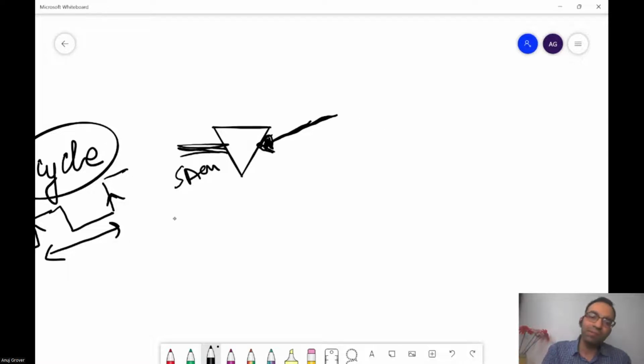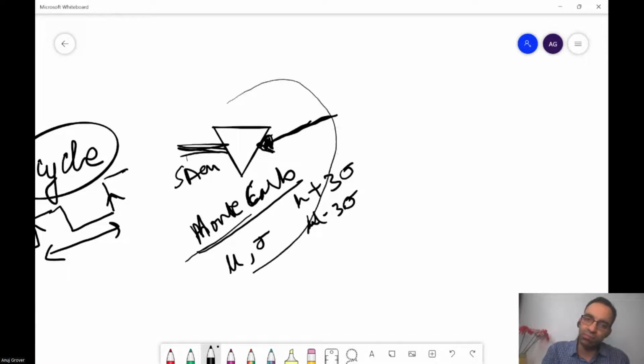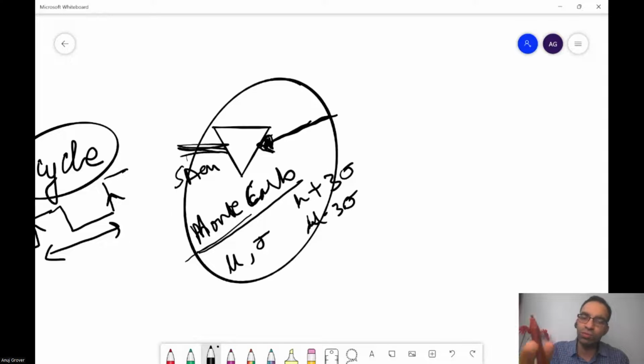So basically, let me give you a top level overview. You will need to run Monte Carlo simulations. And you will then need to look at the statistics of those Monte Carlo simulations in terms of mean and sigma. And then we will estimate mean plus 3 sigma and mean minus 3 sigma offset requirements of the sense amplifier. Okay. So what do we simulate? What is our stimuli in that Monte Carlo simulation? For this, I want you to talk to your seniors.